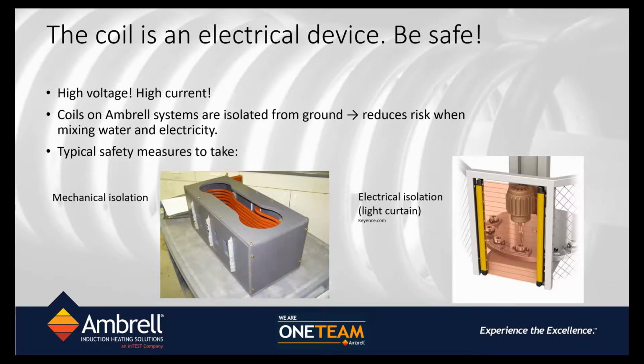However, we do have electrical currents flowing through this coil, so we can't ever assume that this water-cooled heater, which never gets hot, is safe. You have to assume that it is unsafe because it has high voltage and high current in a lot of cases. Even though every manufacturer of today tries to make sure that the induction heating coils are safer and isolated from ground, there are older systems available where it's not the case.